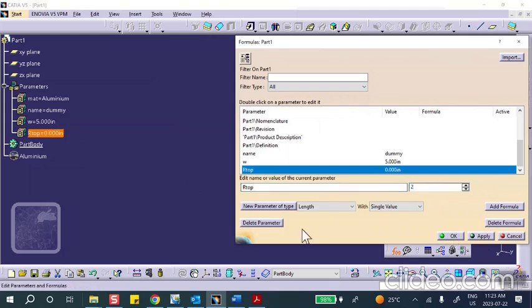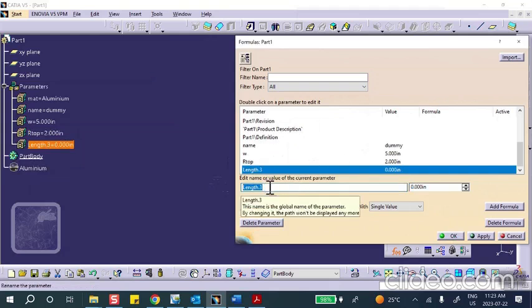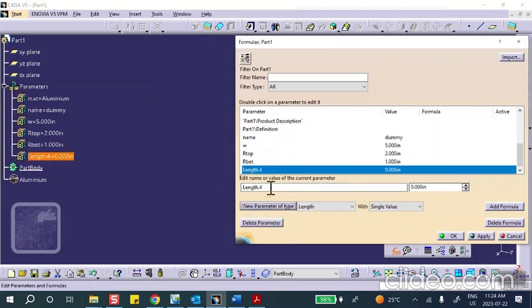You don't even have to say apply, just say a new one. Just watch out and make sure they're created, because occasionally I didn't pay attention and it was not created. Next is R bottom, big R B O T, and the value that I am using for it is 1. New one. The next one in the tree is big L, that's the pad length. I will make it 2.